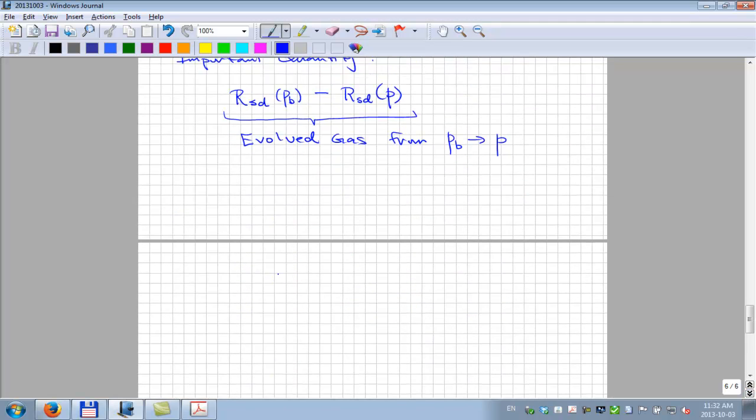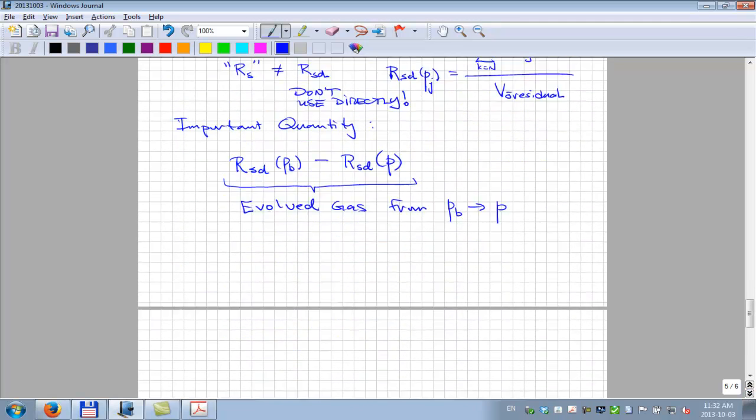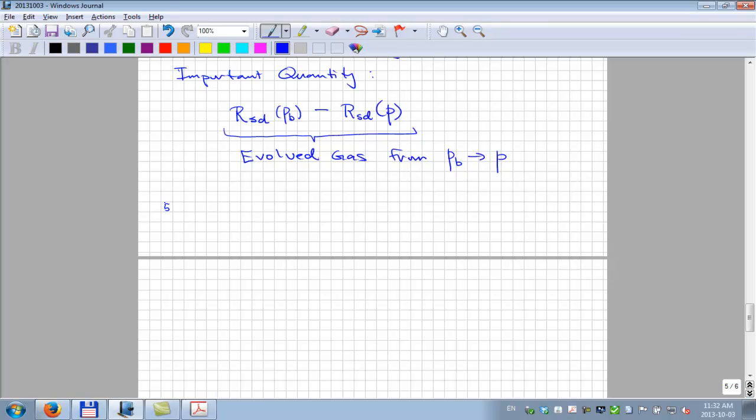The gas density, we need that. But basically this Z factor is reported, but that is being calculated as pressure times the volume that was removed, divided by the moles that were removed, gas constant, reservoir temperature.